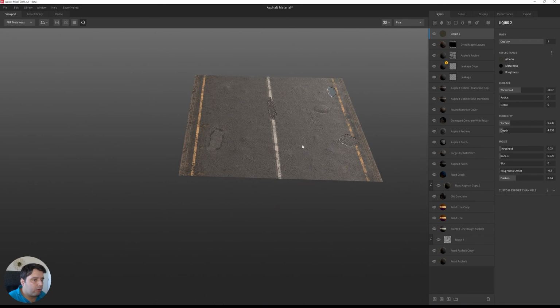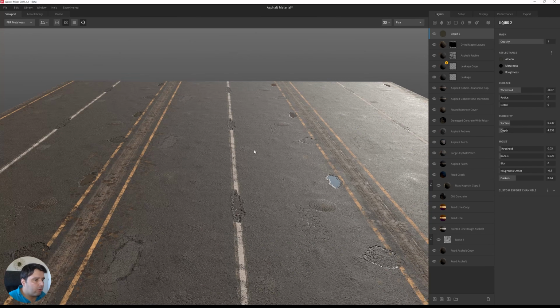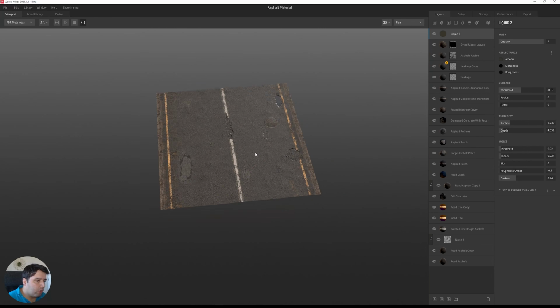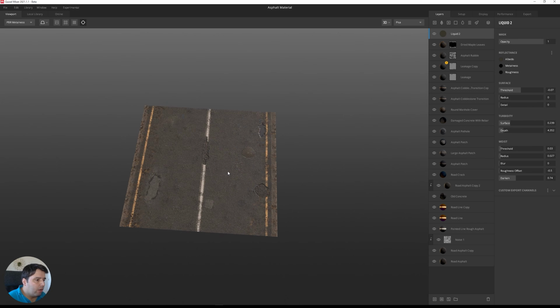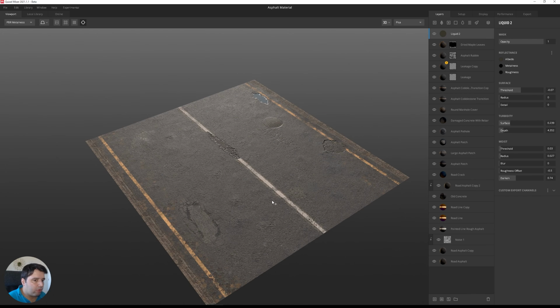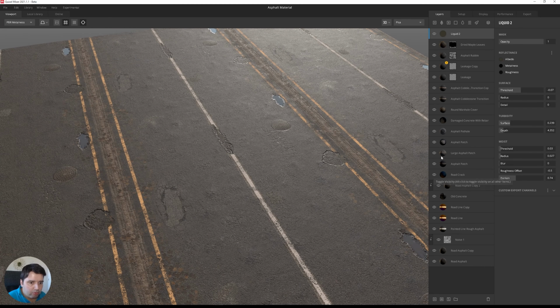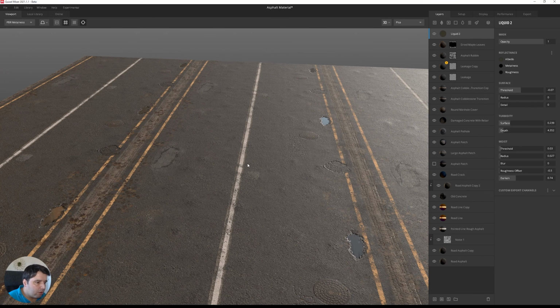And then when you're finished, you can see how this material is repeating by pressing T. Okay. And you will see all of these repetitions. So what I suggest you do is, on your 3D model, cut the geometry into square sections, and then you have a material like this for one section. For the next section, you would create a material that doesn't have this part. So for example, this asphalt patch, you remove it, and you'll not notice this repetition so much. This one you can also remove, so you can have one material that is a little bit more clean and another one that has a little bit more damage.